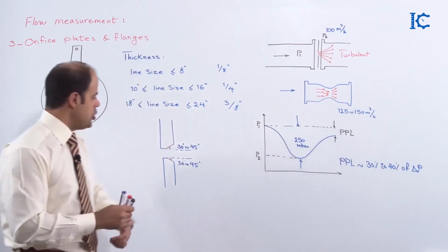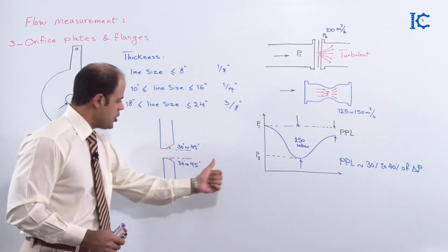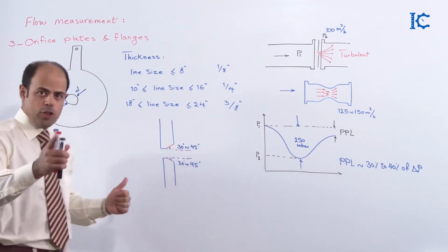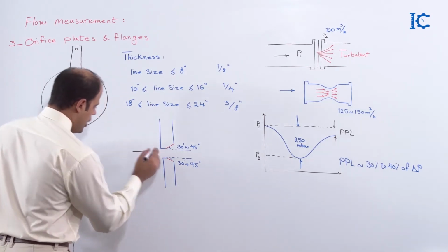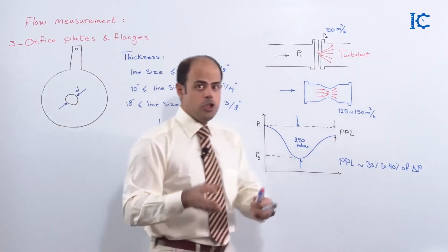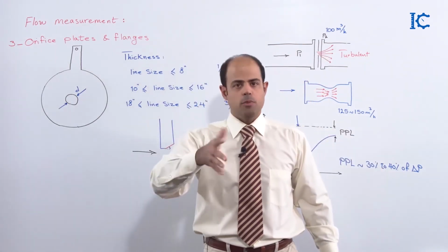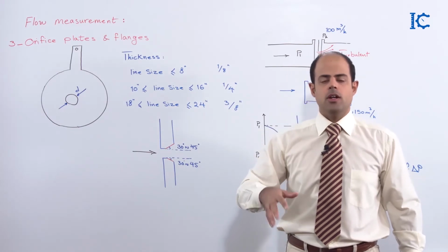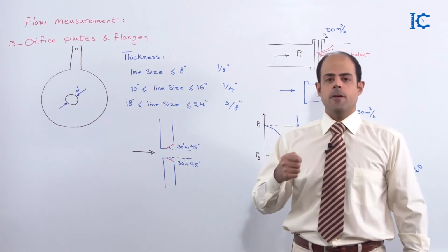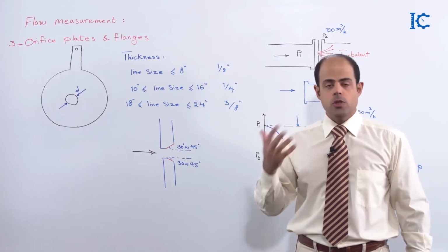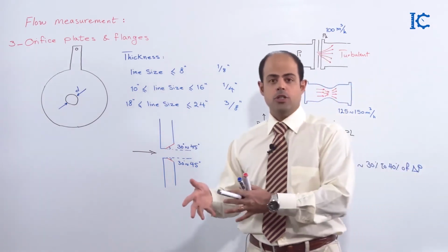Maybe you have this question: where should the fluid pass? From left to right or from right to left? I'm totally sure you know the answer to this question. It must be left to right. Do not forget this when you have the orifice. Do not make any mistake and put it vice versa, because unfortunately in this case the measurement is going to be totally wrong.